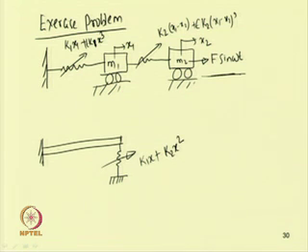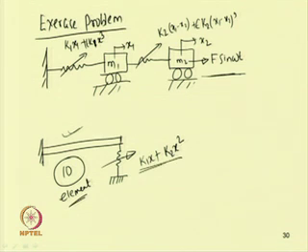As one can take multiple degrees of freedom here, one can use the finite element method to solve these problems. So, by taking 10 elements, one can write the equation of motion, add this nonlinear spring to the system, and also add an external force equal to P sin omega t to solve the system.